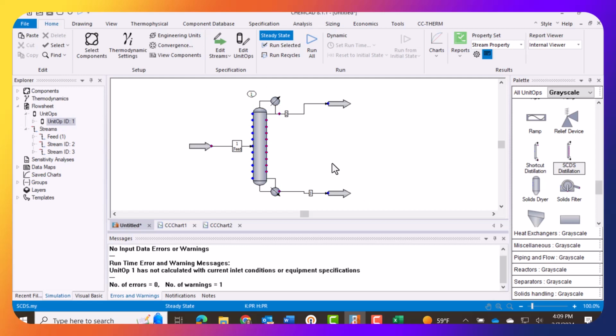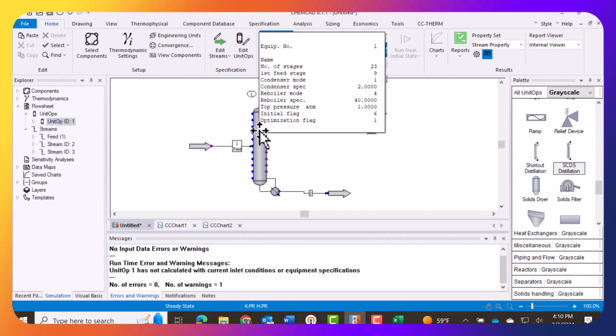Again, I did not enter the distillate rate of 60 kilomoles per hour, because this requires me to put something in about the reboiler. Every once in a while you get something where you don't know any of this, and you have to make a guess, run the simulation, and then check the variable that they gave you. That does happen now and then. So, all right, I am ready.